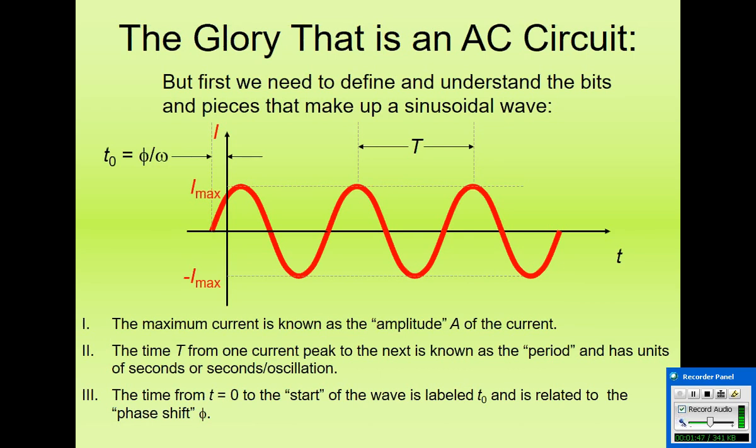We also have another quantity that we're going to have to worry about, and that is called the phase shift. Not all sine waves have to start exactly at the origin, like sine x starts at the origin, but we're going to find that sometimes there is a deviation in where the quantity is in its oscillations when it starts. And the quantity that allows us to accommodate that is the phase shift. So get used to that. We're going to be taking a close look at it as we go through the different circuit elements that can be found in an AC circuit.